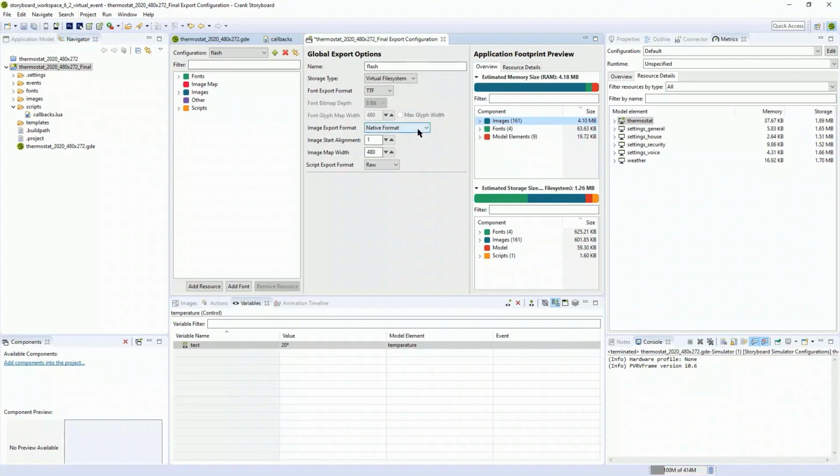What we can do is switch to another optimization, which is pretty cool. For example, if I choose direct RGB 565, which is what I showed earlier, those images are stored in 16-bit RGB format on disk in Flash effectively. So those are streamed directly from Flash in uncompressed form straight to the frame buffer, which means that now we're not using those intermediate inflation buffers and CPU cycles. We can use the DMA engines to draw those images from Flash straight through to the display buffer.